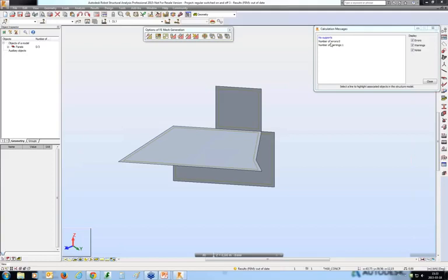If you do that for two neighboring panels, it may happen that at the common edge you have two overlapping nodes, each created during the generation of the meshes for each of the panels. It is at the stage of the model generation that these two nodes are actually merged. So if that model generation was not performed, you actually have two separate nodes and an incoherent mesh is reported.